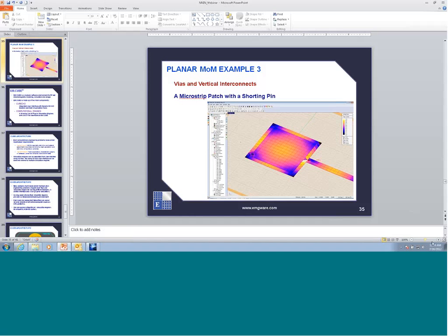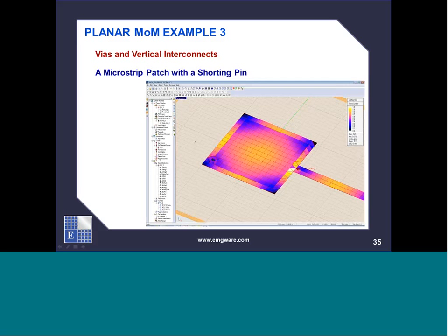Okay, thank you. If we had time now, we could also show the effect of the via, but again, you just put a via simply there, and it perturbs the currents, and you can put a bunch of vias here. You can use them as thermal vias, for example on a resistive pad, or on a DC bias pad. So depending on the application, you can interpret it as an antenna or as a signal pad, whether it's a circuit or a radiator.